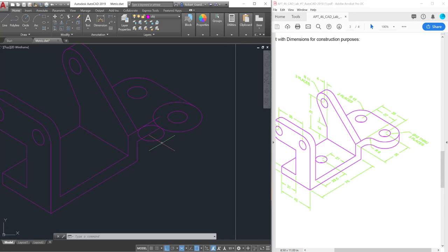I should point out, in addition to not being able to use the offset command or the fillet command for doing isometric views, you also cannot track with the TK option. So that's not a viable way to work when you're doing isometric drawing. So you have to instead use multiple movements or multiple copies, or draw construction lines and snap to them if you prefer to use that methodology.